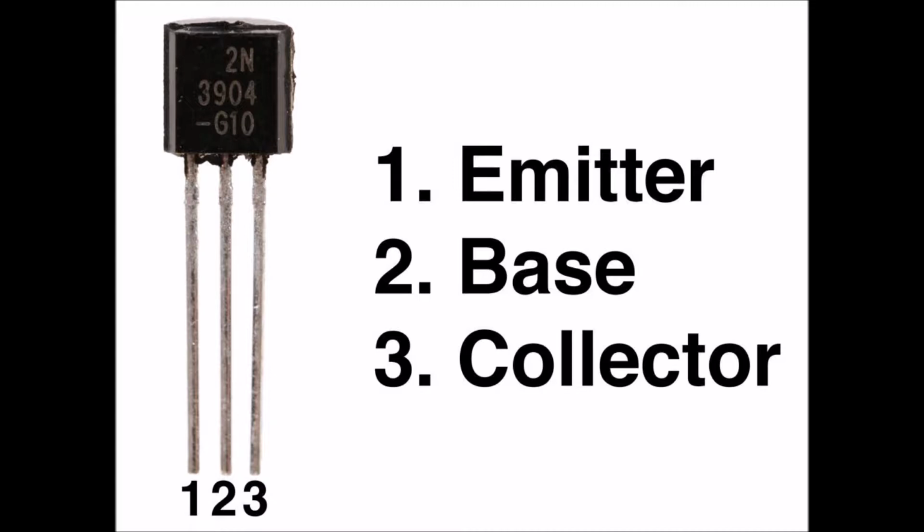We can tell from a schematic diagram whether the circuit designer means for a transistor to be NPN type or PNP type. Once we realize that the arrow always goes with the emitter, we can identify the three electrodes without having to label them. In an NPN transistor, the arrow at the emitter points outward. In a PNP transistor, the arrow at the emitter points inward.